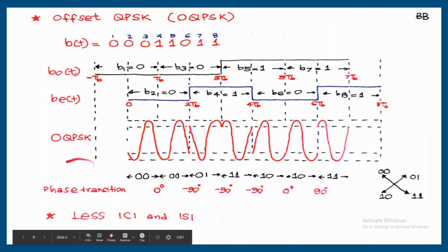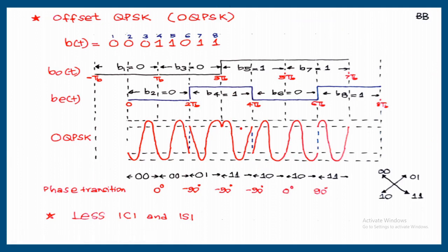This you can see the previous QPSK waveform. Next is 1 0, from minus root PS up direction. One cycle is completed. Next combination is also 1 0, so start from minus root PS, one cycle is completed. Next combination is 1 1, like this case 1 1. Start from plus root PS, one cycle is completed.